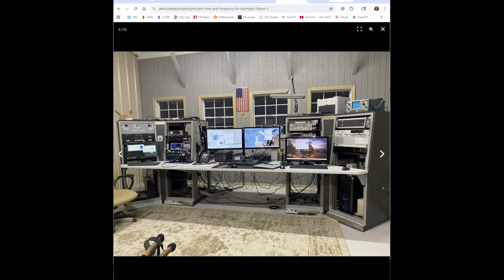Then to the left of that is a variety of power supplies, and up on top is a backup system, which does the identical job as the main system for analyzing data, except it collects its data from a coax cable that is connected to a 3dB splitter at the feed behind the first LNA. And right now, both systems are recording data in real time from a beacon simulating the satellite.